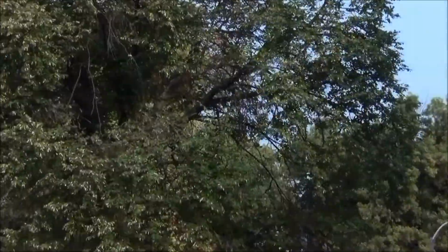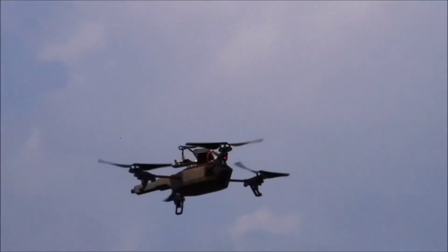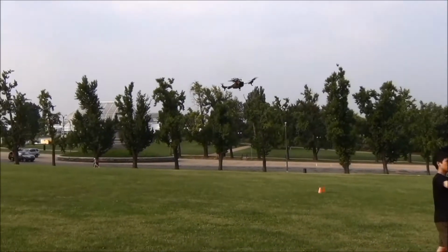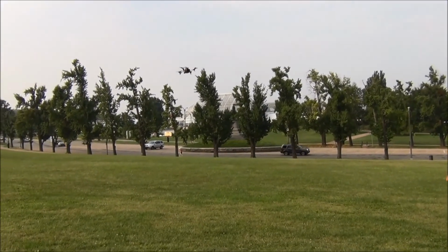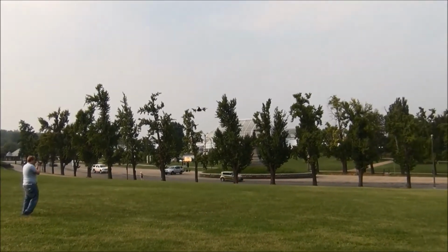Developing for the AR.Drone is challenging for a number of reasons, not least of which is a flight controller that requires 80 to 95% of the CPU. If care is not taken to evaluate drone logic efficiently, the flight controller will be unable to adjust to its environment and the drone will destabilize, causing it to fall from the sky.